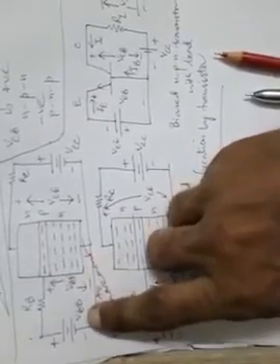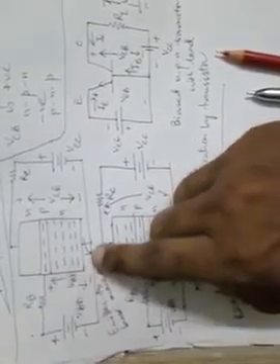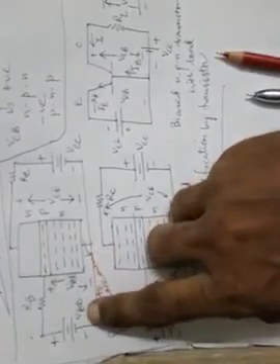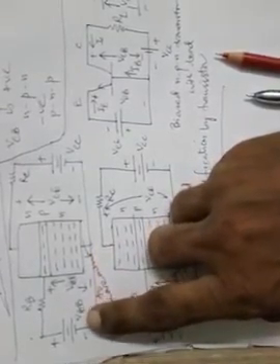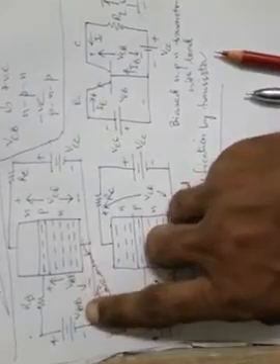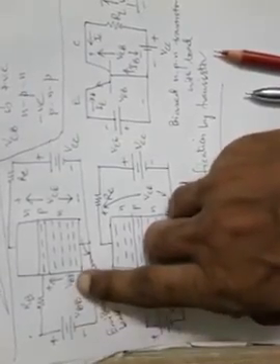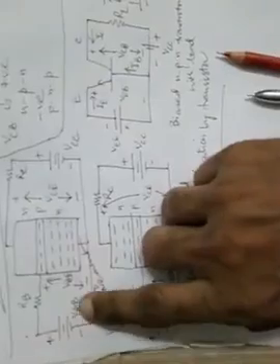So once the base emitter junction is forward biased, it requires at least 0.7 volt to be supplied from VBB to this VBE, so that the junction is actually forward biased and the electrons start to flow. Once VBB is greater than 0.7 volt, that is the barrier potential, the emitter electrons will enter the base region from the emitter region.